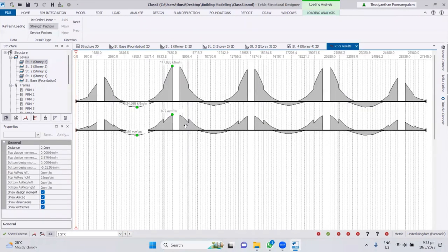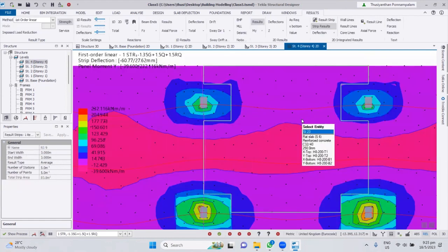Okay. So here automatically we know, right? Our required rebar is almost half of the X direction, because the X-axis span is 9 meter and this is only 6 meter. So automatically our rebar is half of the X direction rebar. Okay. So now you know how to calculate the rebar. After you calculate the rebar, you can detail your slab.